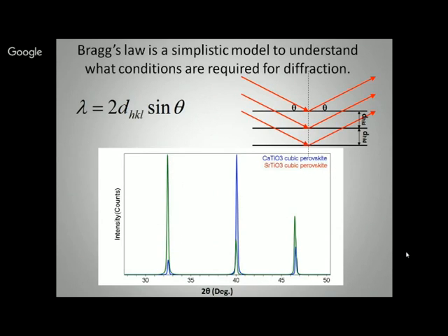In Bragg's law, you can see in the subscript of d there is a value known as hkl. These are known as Miller indices. If you remember your basics of solid state, these are the Miller indices, which identify a particular plane. Suppose in this case you are at the first angle, around 33 degrees, where you have a peak. One is in green and the second one is blue. The intensity of green is high, but the intensity of blue is very low.